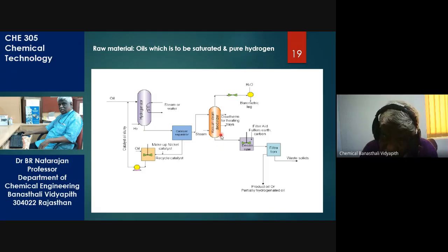Then this is a vacuum deodorizer. The reason for doing it in vacuum is when the conditions are severe. Severe means say 50, 60 degrees, 80 degrees. Then it's not allowable to put this into that. Right? That way we do vacuum distillation.